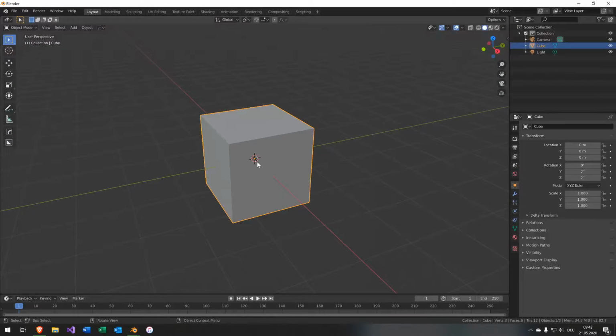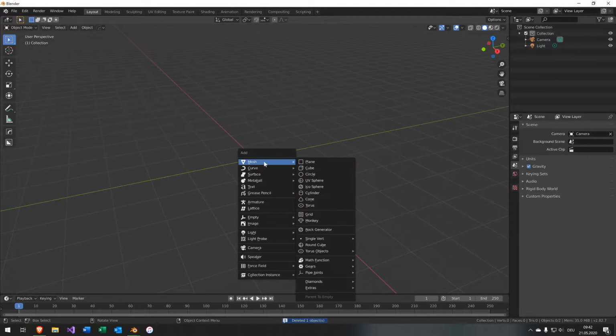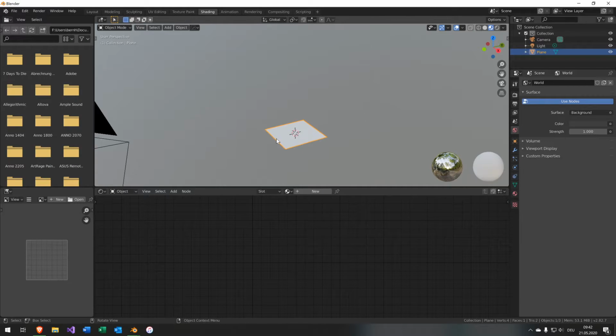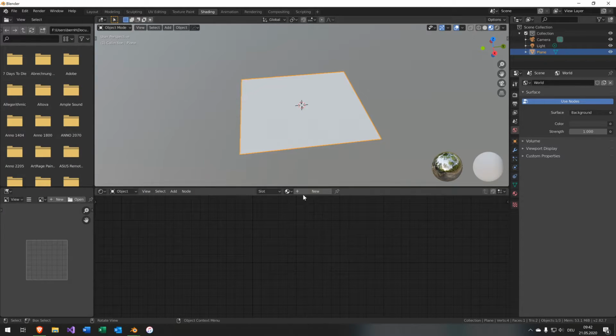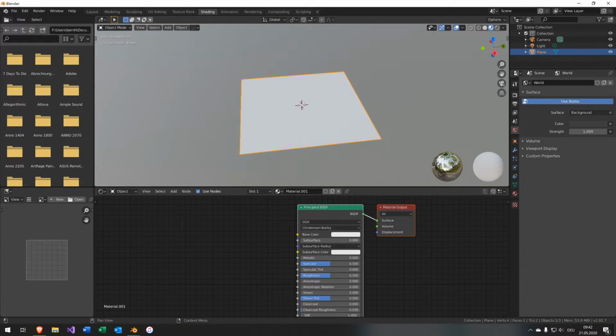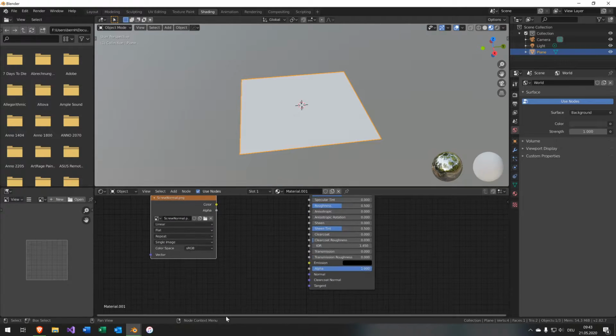I'm doing that right now, and we're creating a new scene, adding a plane, and this plane is our decal. Now we're going to create a material which has all the information that we baked in the first place. I can simply drag and drop the images from my Explorer into Blender, which will automatically create an image texture node that I can use straightforwardly.